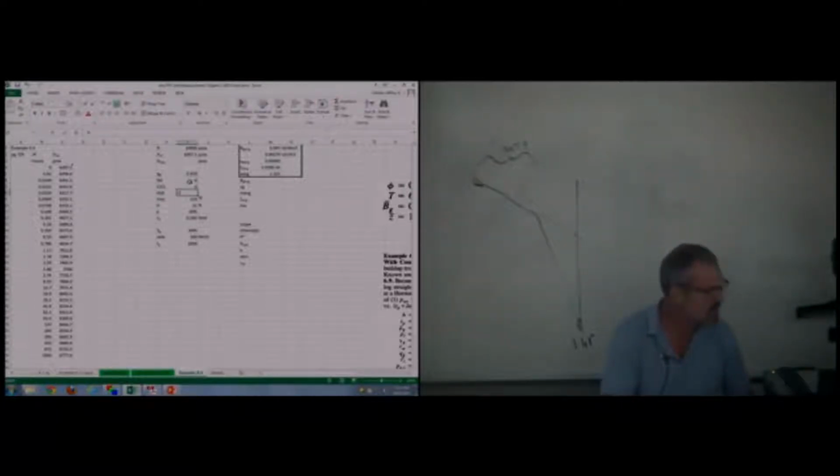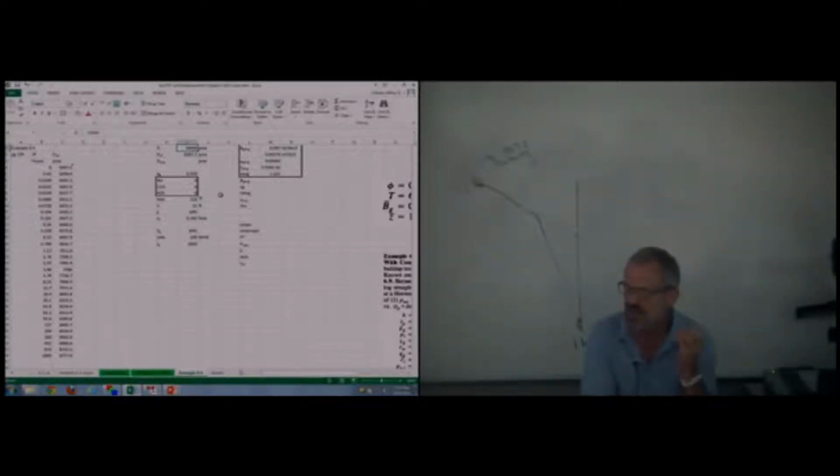Because I know that we're coming up with a problem that's going to have impurities. Okay, we got composition, we got reservoir temperature, and so we can calculate fluid properties. Again, I fictitiously made initial pressure 10,000 pounds to show that in general we don't know. I could make it 8,000 to make it 1,000 pounds less than what they said. We're actually gonna capture this when we capture pseudotime.